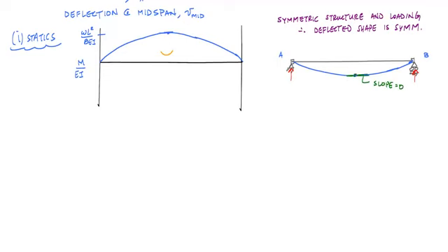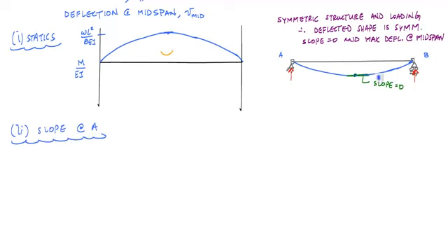When you apply the moment area method, knowing where the slope is 0, or the deflection is 0, or where the deflection is maximum is really important in setting up a reference, because the slope calculation and even the displacement calculation using moment area methods are all relative. Now that I have a sense of the deflected shape, I can calculate the slope at A. Because I know there's a point along the length of the beam where my slope is 0, I can use that as one point.